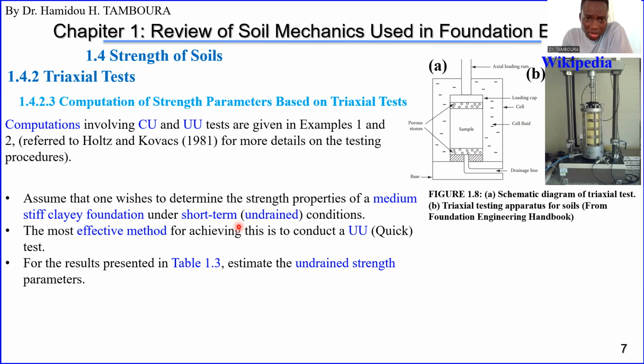Always, if you are dealing with clay in short term, the clay will not have enough time to drain water. In that case, it has to be undrained condition. That is very important for you to understand.